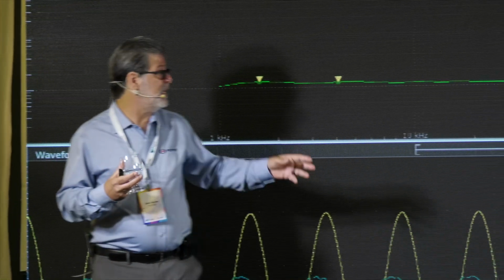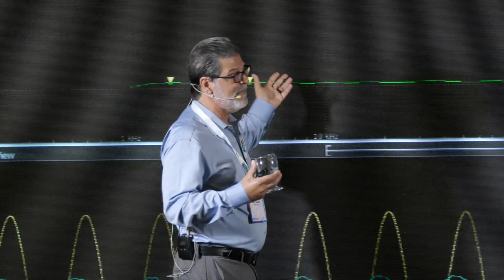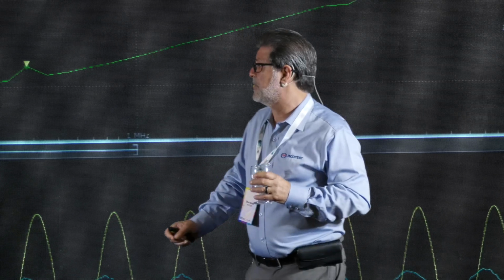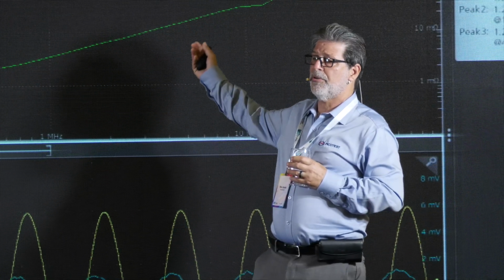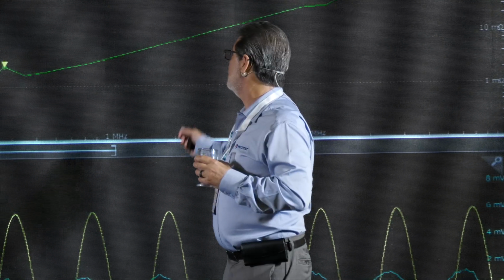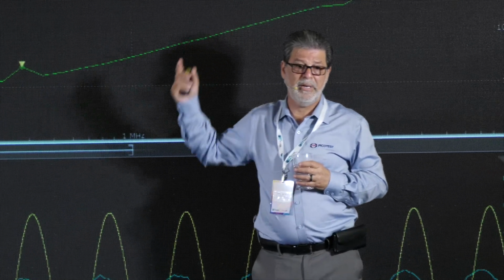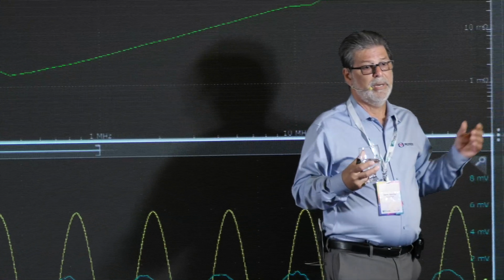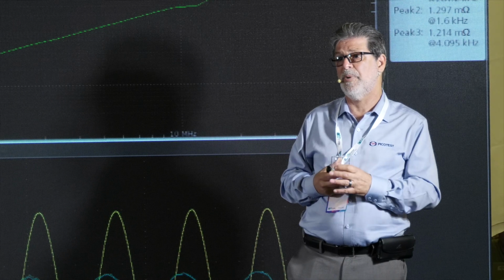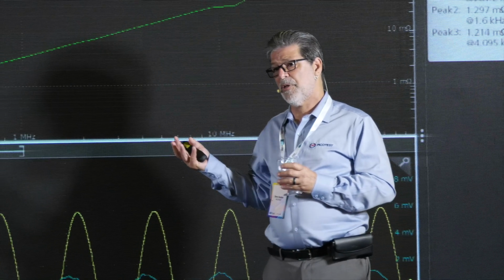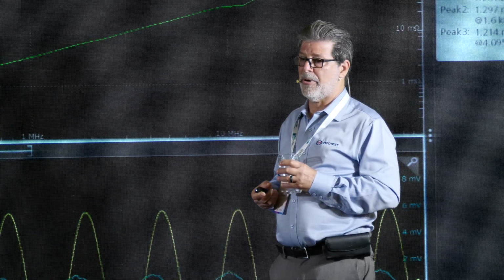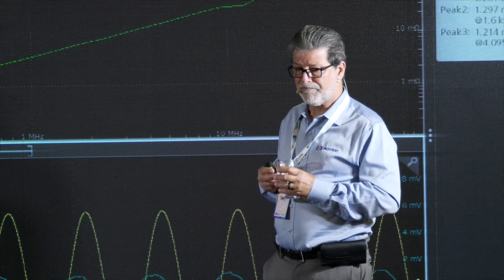Okay, I think we're out of time, but I just wanted to show you this picture because it's never been done before, it's never been seen before, and it was really exciting for Picotest to work on this. But that is two-port shunt through vector network analysis in an oscilloscope measuring a 1 milliohm resistor with a 400 picohenry excess inductance. And so now within the single instrument, we can measure spectral content, we can measure time domain, we can measure frequency response using a 3-port FRA, and we can measure vector network analysis using a 2-port S-parameter analyzer, all within a single instrument.